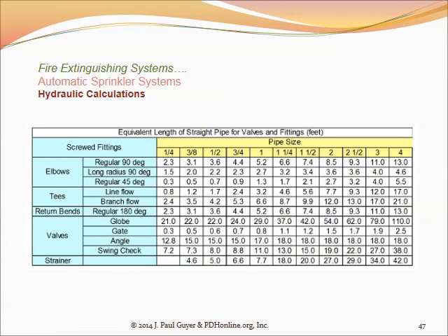Now, for purposes of doing this calculation, the location where you assume the fire is breaking out is the most hydraulically remote location in the building, and typically that's the most geographically remote location in the building, remote from the point where the water enters the building. And so you've got 50 psi coming in, 20 psi you need on the fire, and so you can lose 30 psi due to friction loss in the piping.